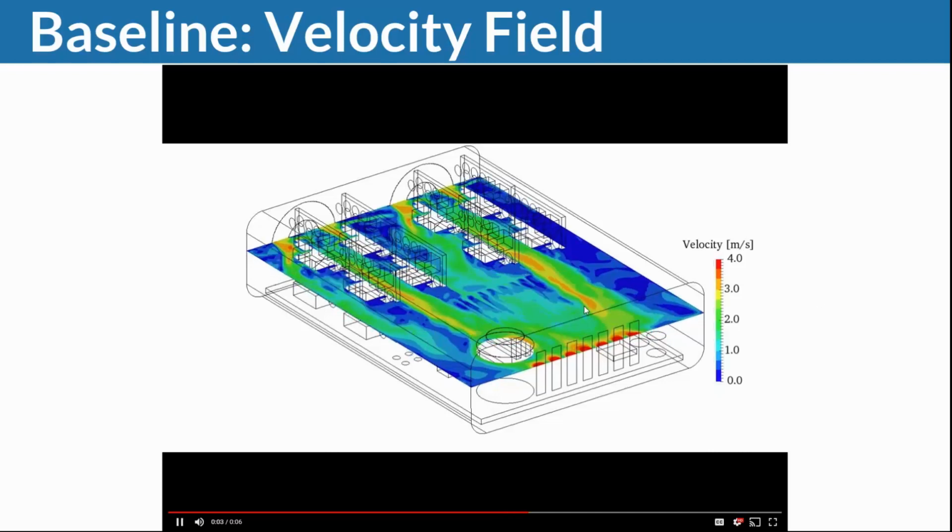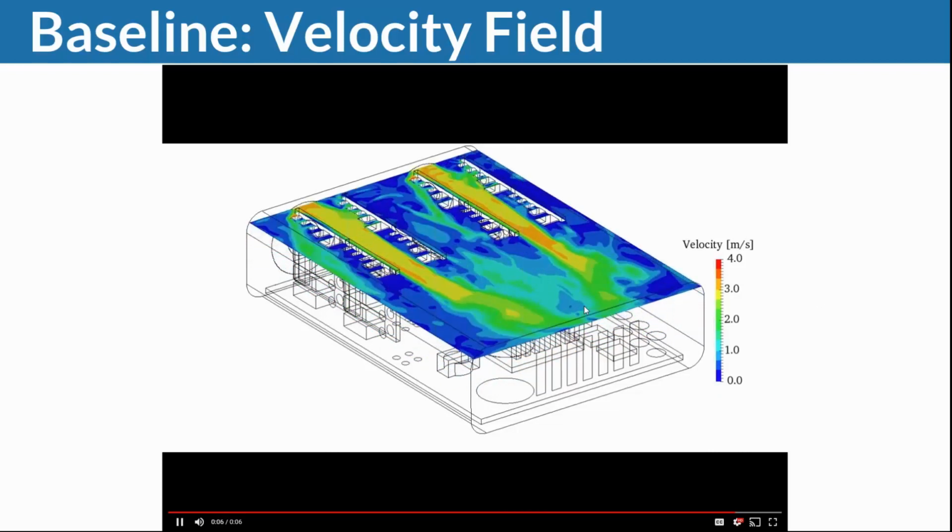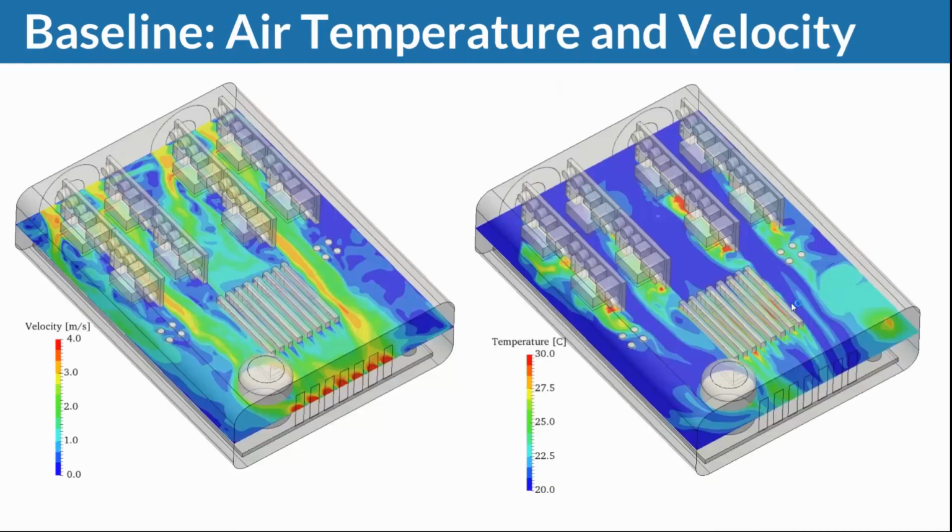All right, just finishing up this video. And now digging a bit deeper into this. This is now a cut section of this initial setup, of the initial fan choice. Intuitively, we said, hey, that's the fan we normally take, so let's just use that one. On the left, we can see velocity color coding here. And as I just highlighted, we can see we've got blue stuff going on here. So there might be some insufficient cooling over here. We'll see in a second.